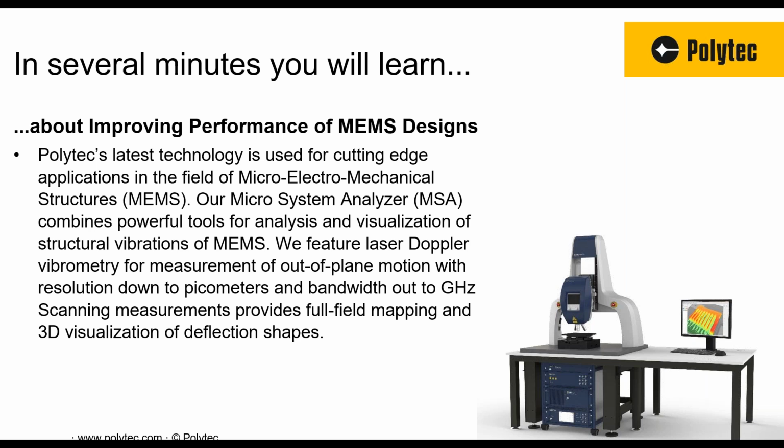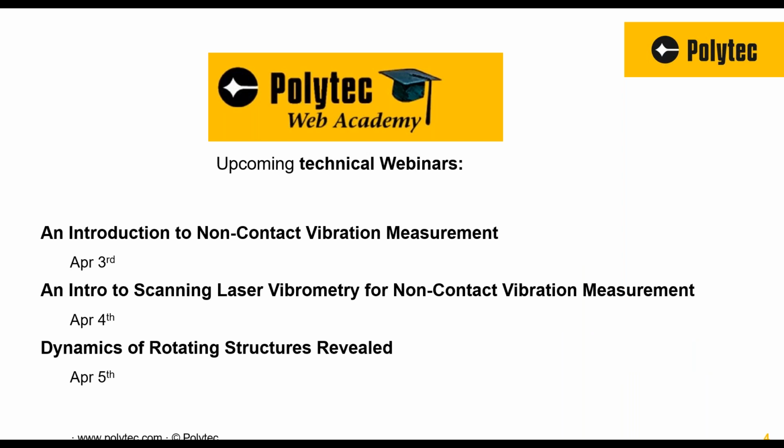And what you could do is either dim the measurement beam, or you can gate the measurement beam on and off. So you can turn it on for a second to do the measurement and then turn it off while the measurement's not running. So that's something you could do in the case where you have something that's thermally sensitive. In most cases, the stuff I showed with the MEMS comb drive, there was no thermal sensitivity to the laser beam.